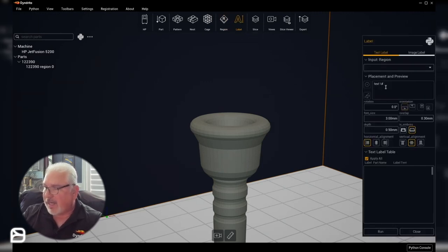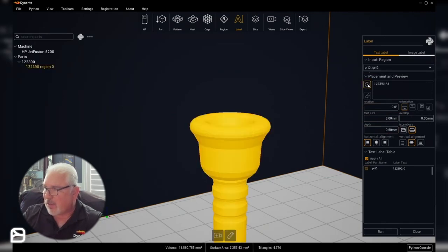There's ways of automating adding this label to define an area, and then you can go ahead and establish center, location, everything about that label, or you can manually come in and just place that label. If I say I want to place this label on that part here, I can orientate the angle by typing in the field, by changing the size, whatever. The pound sign is the variable to numerically label these parts sequentially. And so if I go ahead and duplicate this part, it's going to number them all.